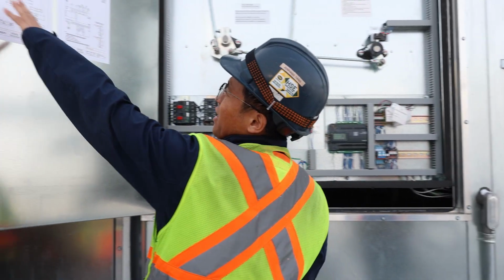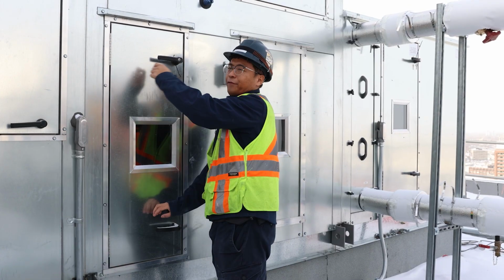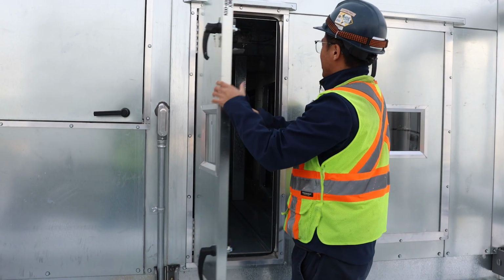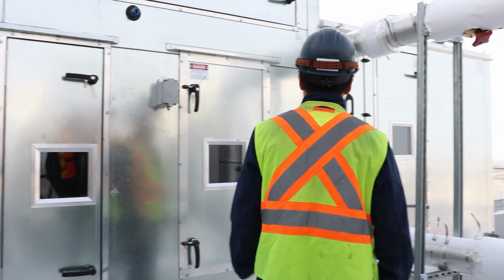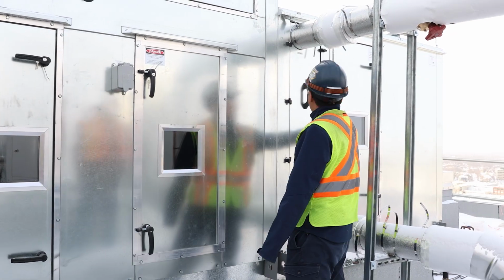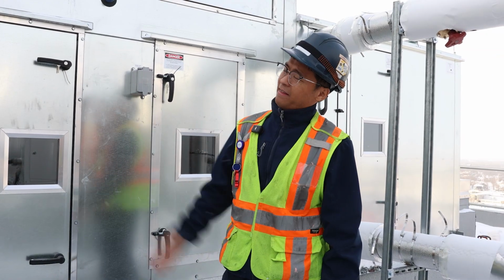And this is the schematic drawing of the unit. So this is the filter. The BMS monitors the filter differential pressure, because the unit is running, the pressure sensor and the filter. And now, this is the supply fan. And inside here, we will have a low limit sensor and a supply air temperature sensor. Yeah, I think that's it for the outside.